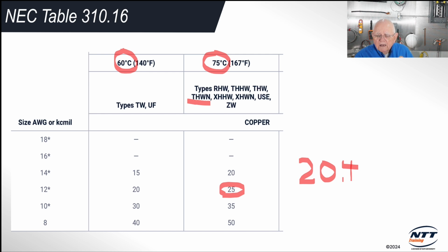And I've looked at the information that comes with my air conditioning unit, and it tells me that my terminals are rated for 75 degrees C. And I've looked at the disconnect I'm going to place in there, and that listed switch tells me that it's rated for 75 degrees C on the terminals. So I decide to use some number 12 AWG THWN conductor to run in this branch circuit.